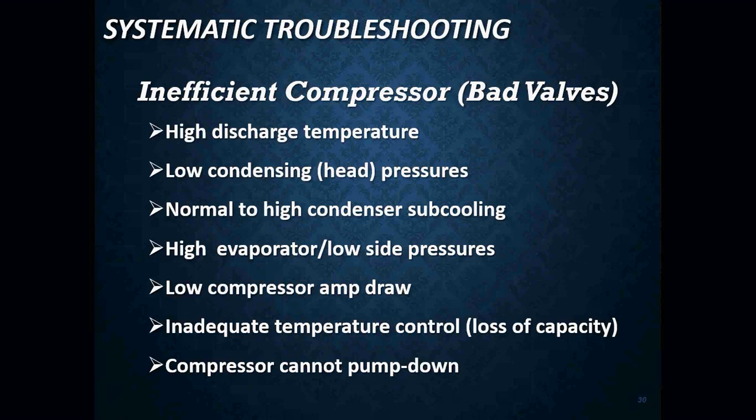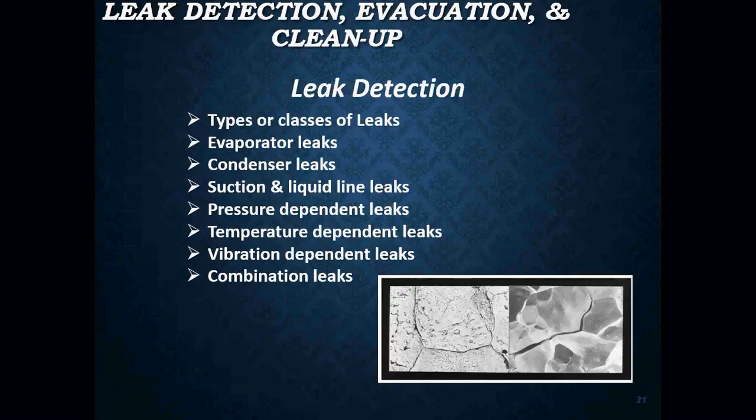Main causes for your valves to be damaged is really liquid slugging of refrigerant or oil. Your superheat is too low, or the valves are weakened by acid or by overheating. That's usually what's going to cause bad valves in a compressor.